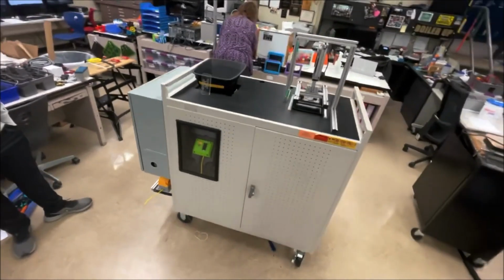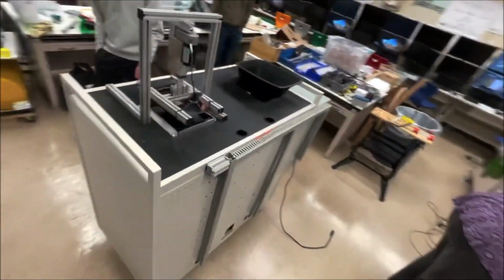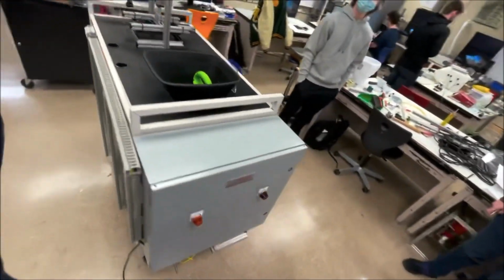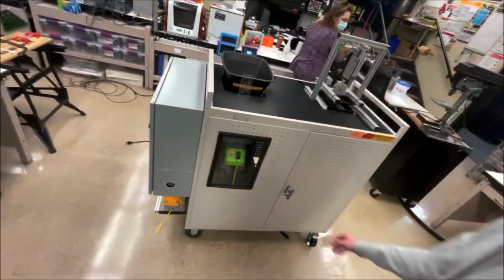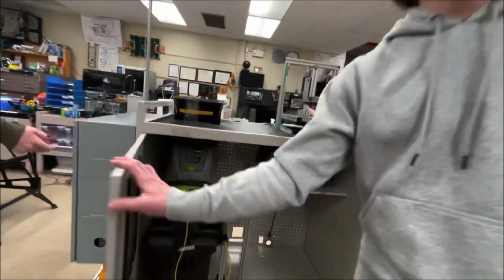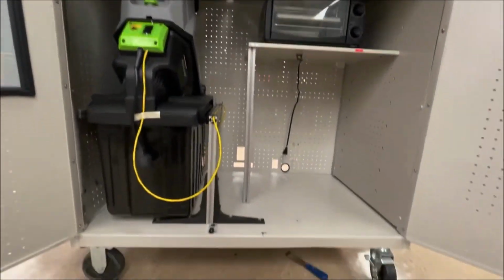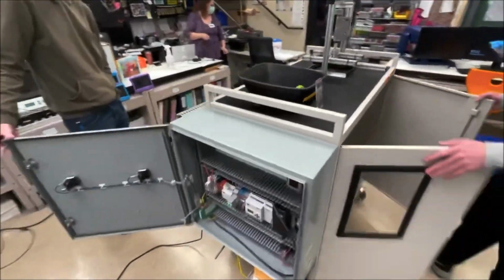We are the Nifty Nerdler Nanoline team from Benton Central Junior Senior High School in Oxford, Indiana. For our project, we are taking used polypropylene hangers and turning them into flat stock for our classroom Glowforge and our CNC machine. We first place our hangers through the 15 amp shredder on the left side of our cart. Once the shredder's bin is full, a sensor will shut it off and the machine operator will get a uniform amount of shredded plastic from it and place it into the toaster oven.